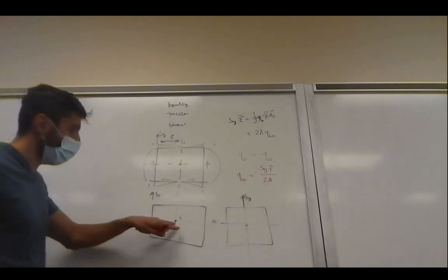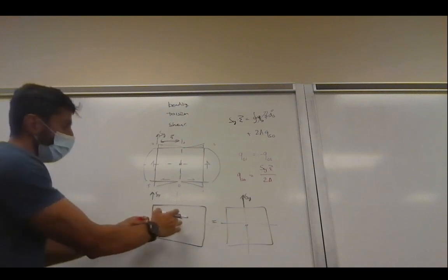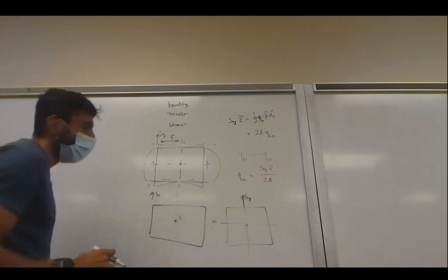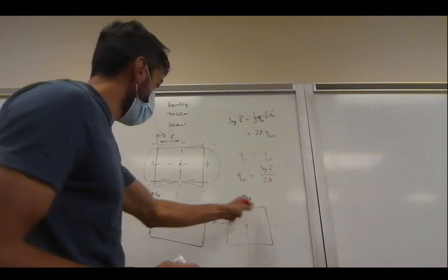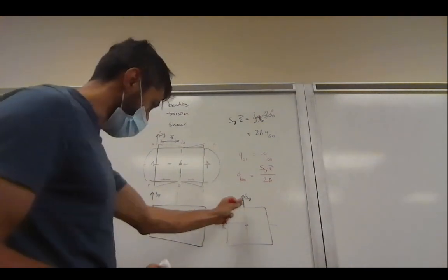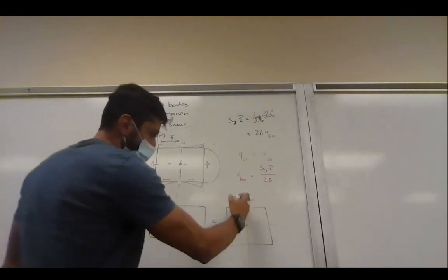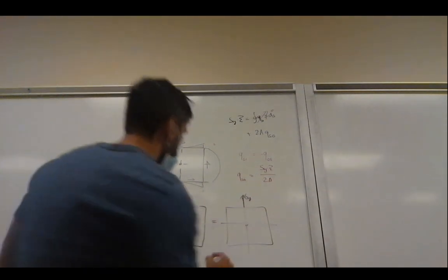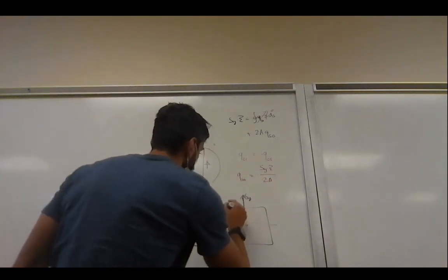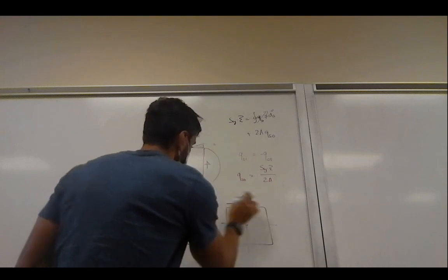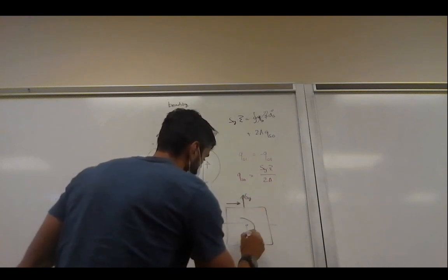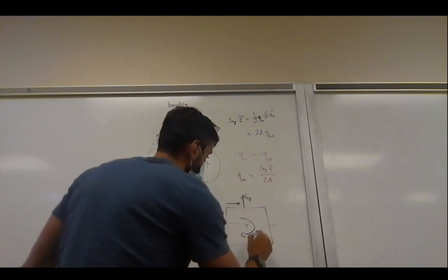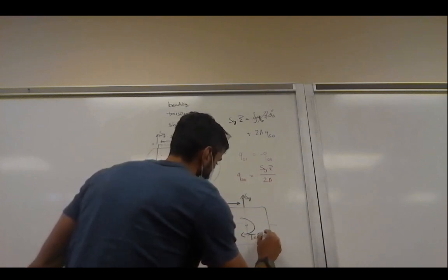By the way, this is doubly symmetric, so we have the centroid and the shear center corresponding in the middle. So I replace the shear force by a moment acting at the shear center, and I add a correction to it. So this is basically the shift creating a moment. So now I have an internal torque T, where T is equal to Sy times Xi.